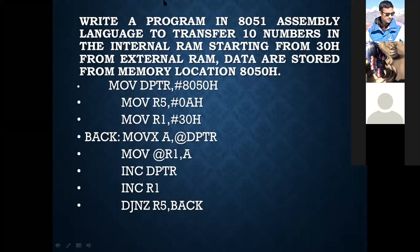Okay. That means R5 content was 0A. So after the instruction, the content of R5 will be 09. So 09 is not 0, so this condition is satisfied. Decrement and jump if not 0. That means the content of R5 will be decremented by 1, and it will check whether the content of this R5 register is 0 or not. If not 0, then jump to a particular relative address.